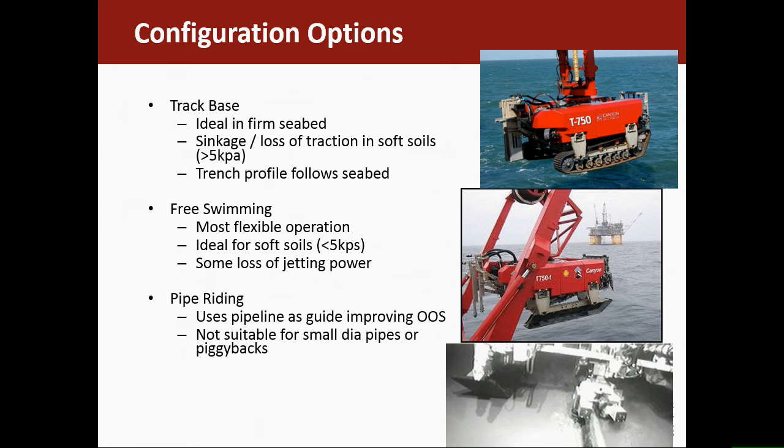And pipe riding is there, where you have some rollers which clamp onto the pipeline, and you can swim along the pipeline or drive along the pipeline. They're not that great because they're only really effective if the pipeline's not partially embedded, otherwise the rollers start contacting the seabed and getting stuck. And if you've got a piggyback, do you know what a piggyback is? I take it you do. Another pipeline on top of a larger pipeline. If that goes round somewhere else, then you can't use the pipe riding rollers. So I know of people who have pipe riding rollers, but nobody really uses them.